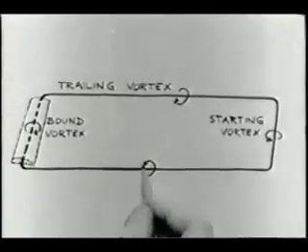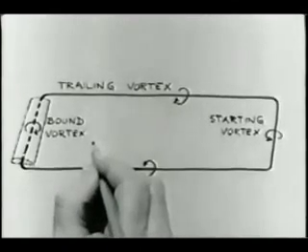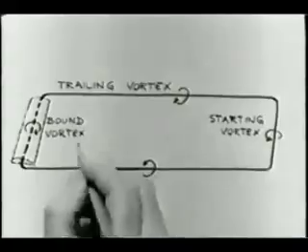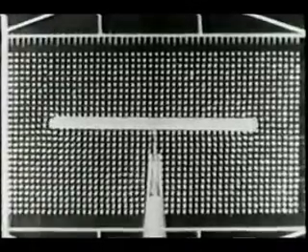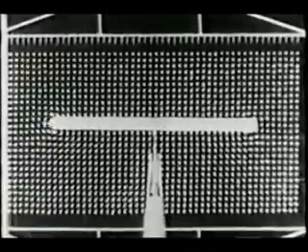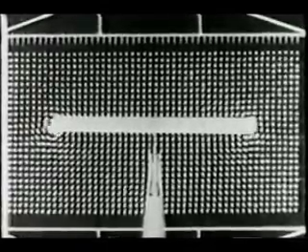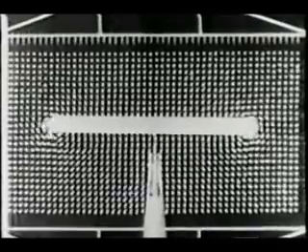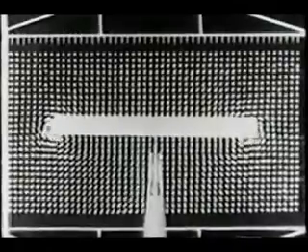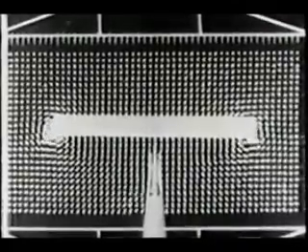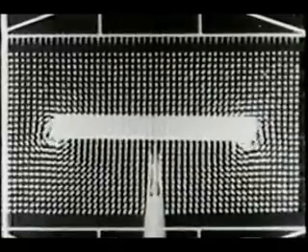Looking at the induced velocity field of the vortex loop, you can see that there are downwash velocities within the enclosed region. These downwash velocities, which you can see in the tuft pattern behind the wing, act on the wing itself. They make the wing appear to be flying through air which is itself descending, and this results in what is called induced drag. The work of the forward-moving wing, as it moves against this induced drag force, accounts for the kinetic energy being stored in the constantly lengthening trailing vortices.